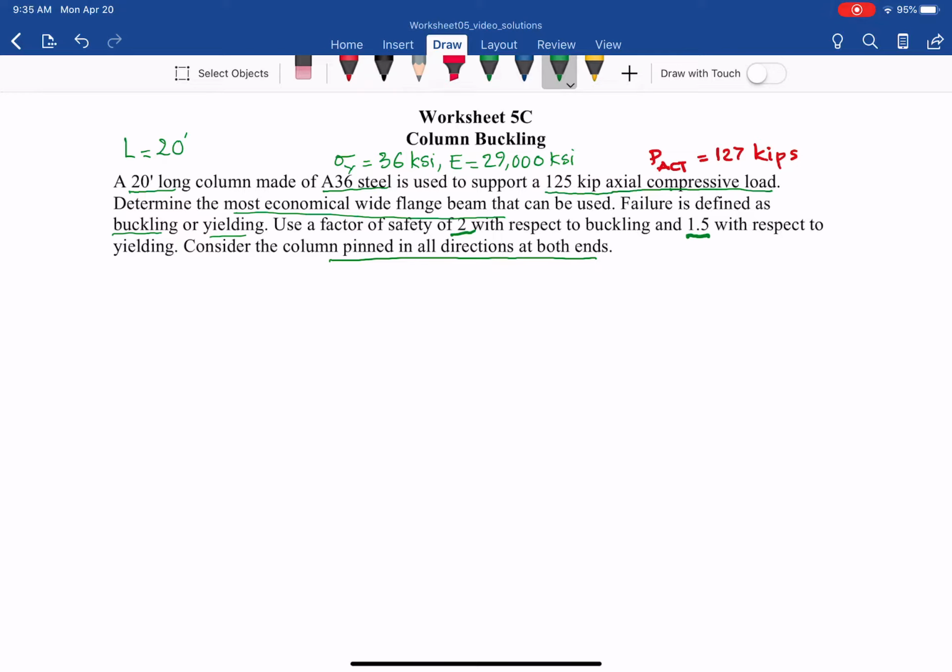So in the Euler buckling equation or the critical load, for the I, the area moment of inertia, we need to get the smallest I among the I's through the neutral axis of the cross section, the smallest area moment of inertia.